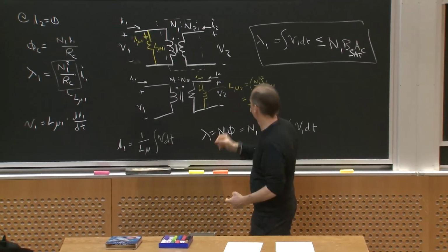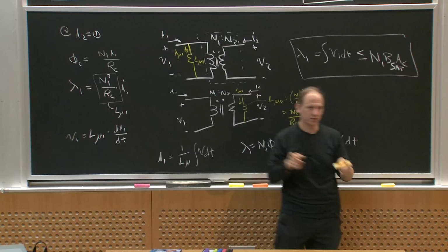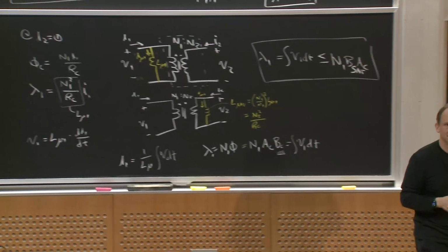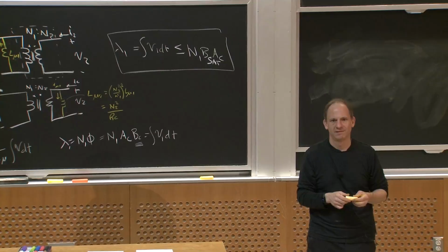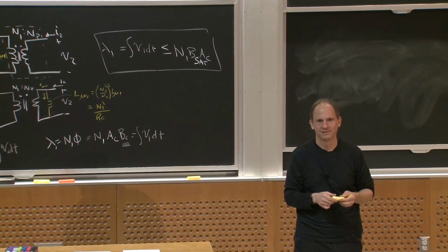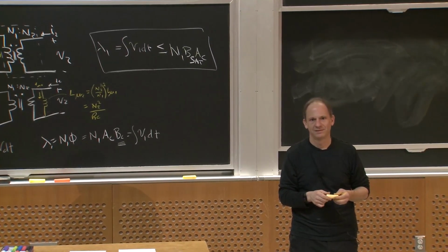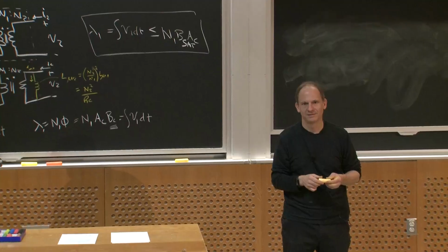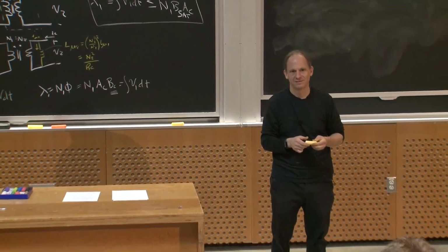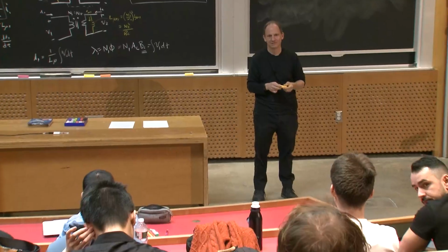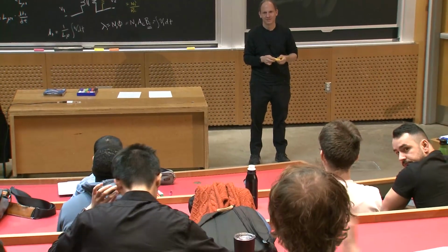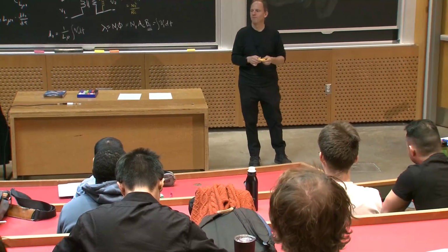The second parasitic, first of all, any questions about that? Yeah. Are there any applications where you could sort of use this, like a switch supply where you're applying DC voltage for a little bit and then you switch it off, and so that way the volt seconds that you have on the transformer are few enough that you don't reach that saturation field, but you're still using it for DC voltage? Is there any use for that?